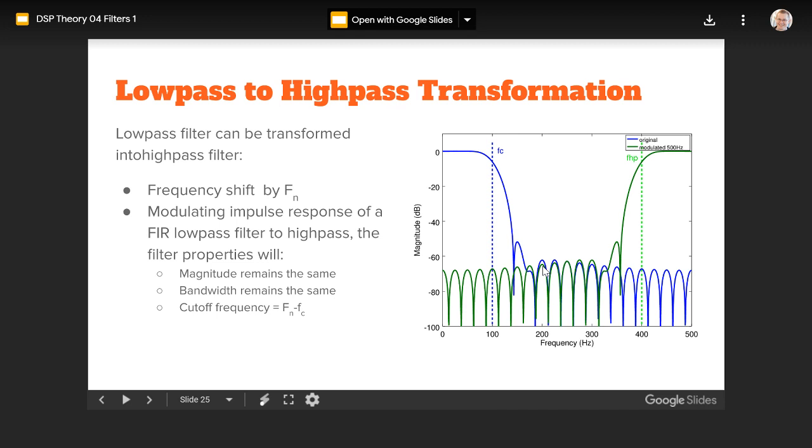The cut-off frequency of the high-pass filter, so FC of high-pass, is the same as sample rate over 2 minus FC of the corresponding low-pass filter. Remember that one. So how the filters are actually defined. If it's defined by the special points, make sure that you have the correct bandwidth. And so there are some places you can make mistakes on the exercise, of course.